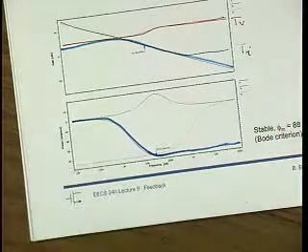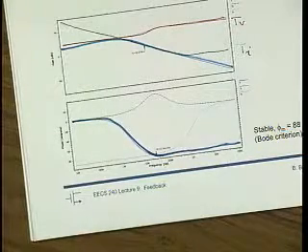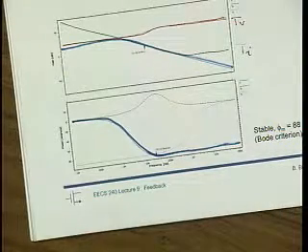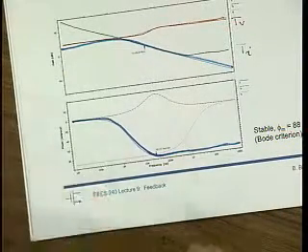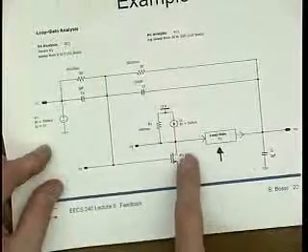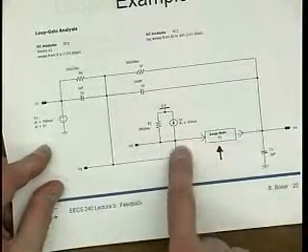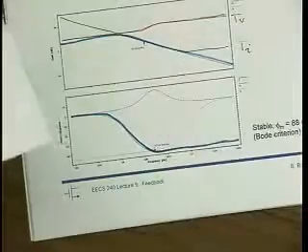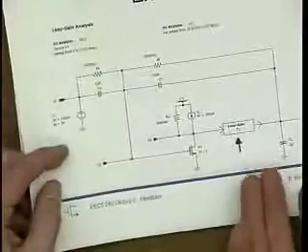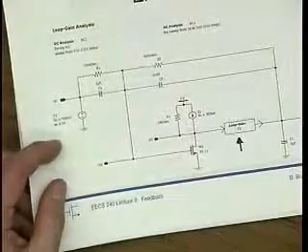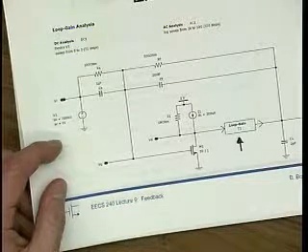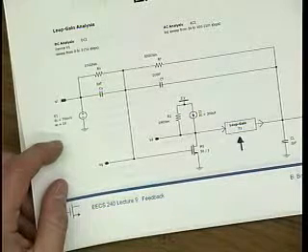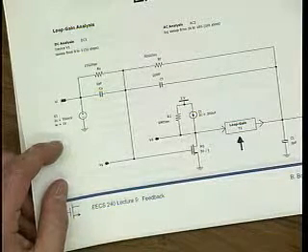So we can use the Bode criterion and get a lot of phase margin. After all, why, for this circuit we have a single pole here at the output. Why don't we get 90 degrees of phase margin? We should even get maybe a little bit better than 90. There has got to be another pole in town. Otherwise, how can you get more than 90 degrees of phase shift? Something must be there.